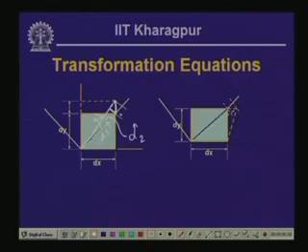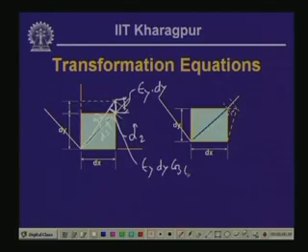The horizontal stretching of this particular element is epsilon y dy as we have seen, and this particular angle is theta. So, this stretching is equals to epsilon y dy cos theta, and that divided by the original length ds will give the value of angle alpha 2.